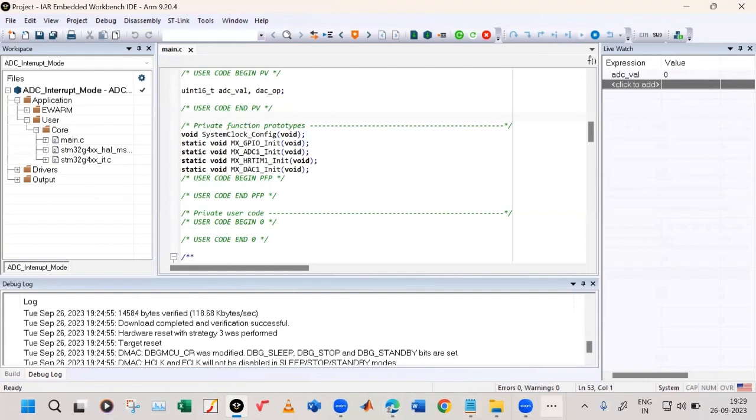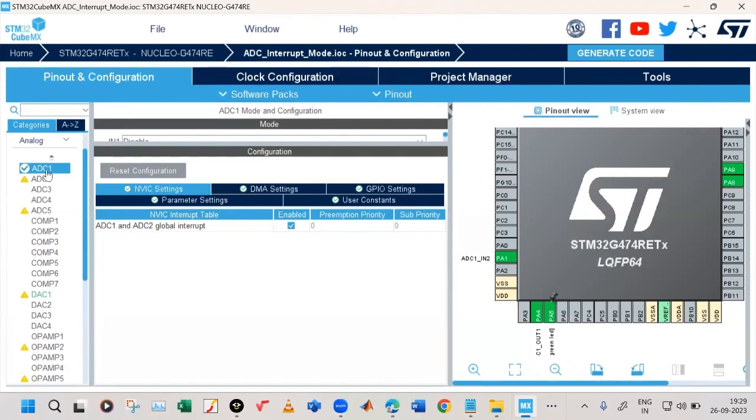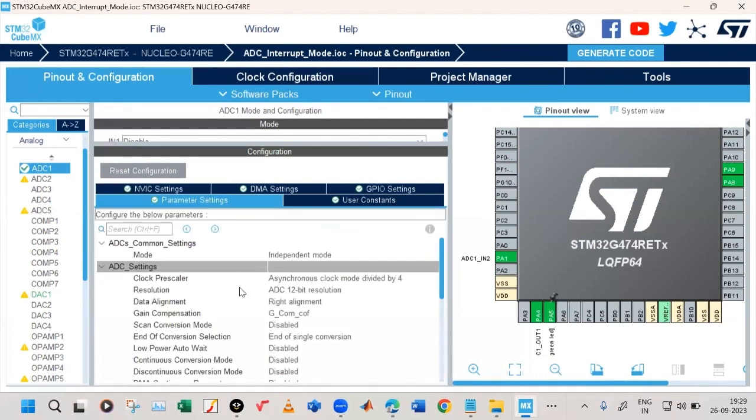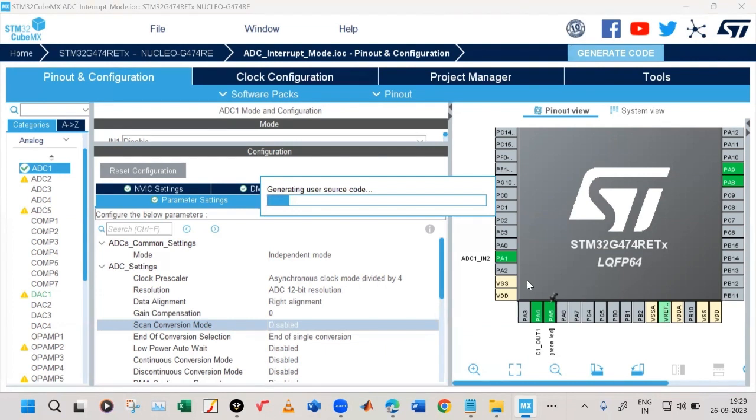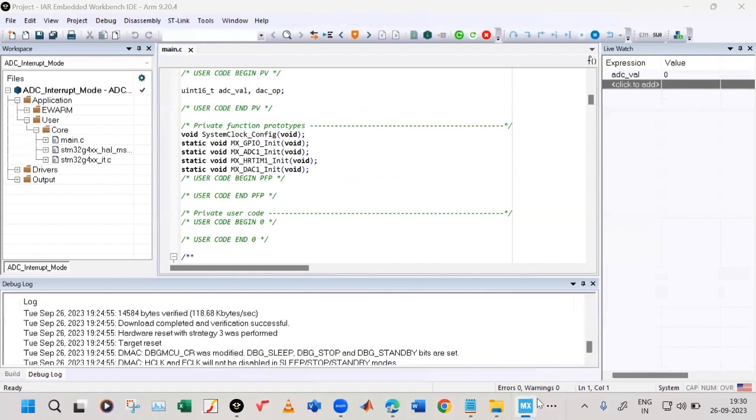Now, what I do is I remove gain compensation. I go to my ADC and remove gain compensation. I give it a default value 0. Sir, here we have connected pin number 30 of CN7 and then the 3V3 pin, right? There's an Arduino connector, there's one 3V3 pin. In that Arduino connector, the 3V3 is there, 0 is also there, ground also there. So I connected that. Now what I did, I made a change.